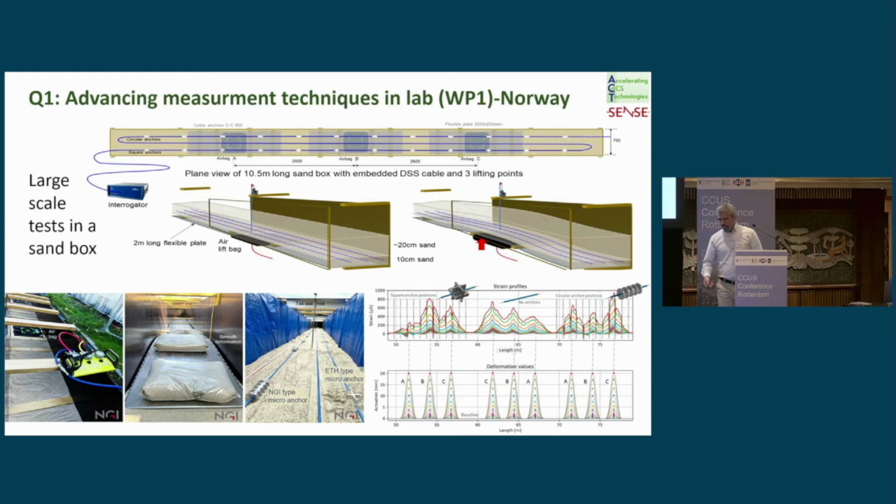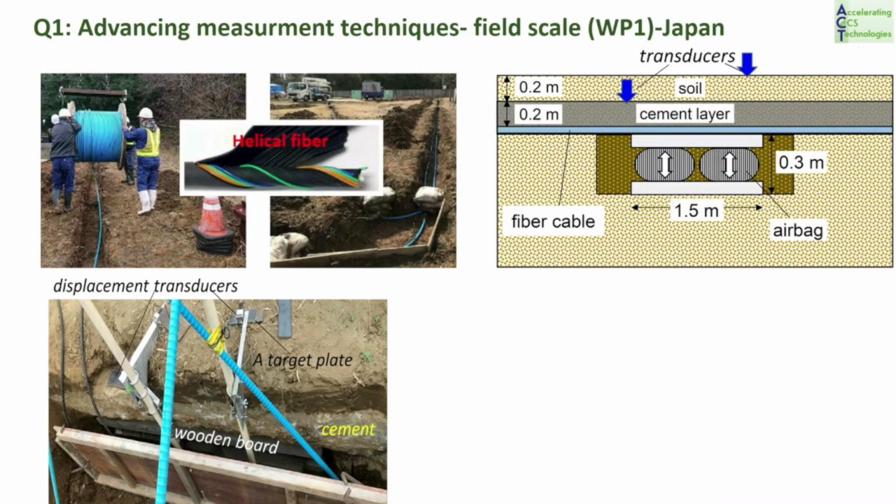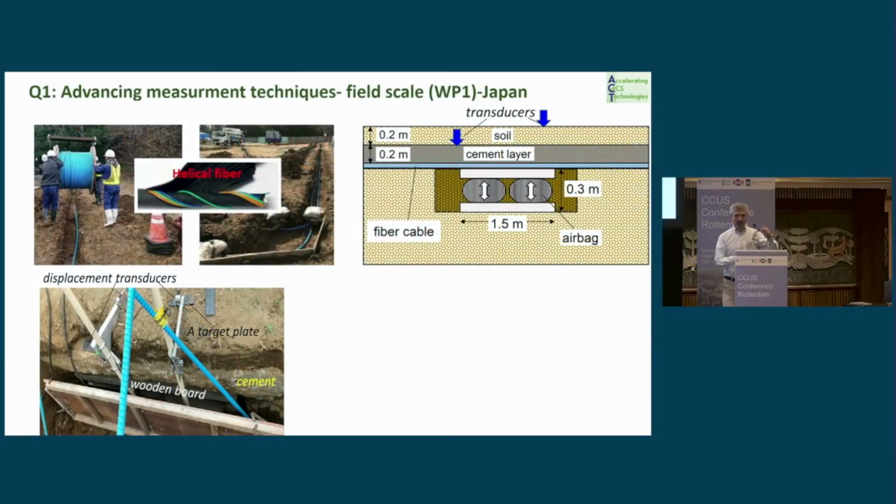So there we can measure strain. This cable is mainly DSS, strain sensing, not temperature or acoustic. So in this case, we show that it will work very simply, without any coupling to the bottom or sand.